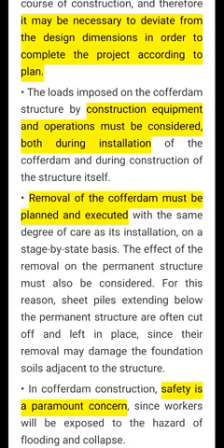Now removal of the cofferdam must be planned and executed accordingly, because these are temporary, not permanent. In caissons these sheet piles are permanent, but in cofferdams these are temporary. That's why the removal of the cofferdam has to be planned and executed accordingly.